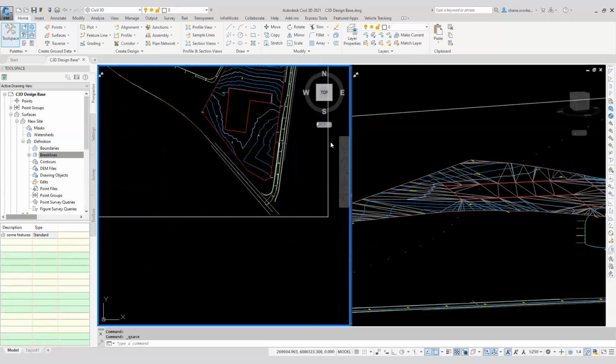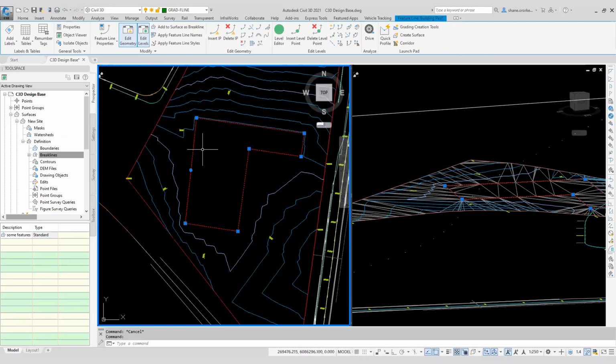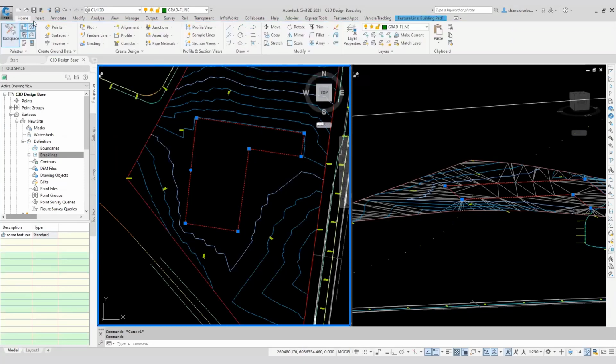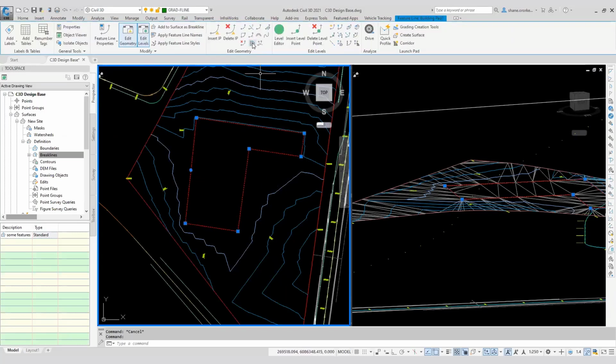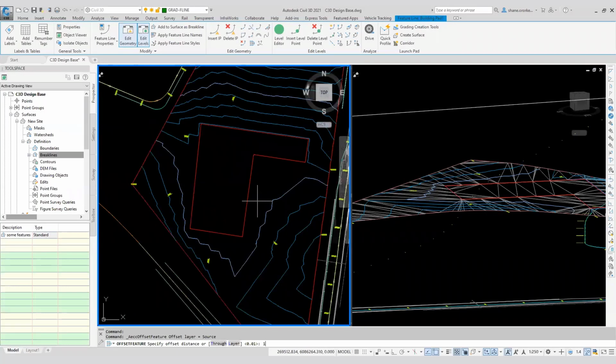Okay. All right, so I've got a building pad. What I want to do with that is create an offset for a footpath around it. I can actually use grading to do that, but I want to play a bit more with feature lines. There's a command here called stepped offset, which you also saw from the Home tab. What stepped offset does is simple to use, and that's what's good about it. You click on stepped offset and type in an offset. So I want a 1.5 meter footpath around this building, so I type 1.5 for the offset distance.